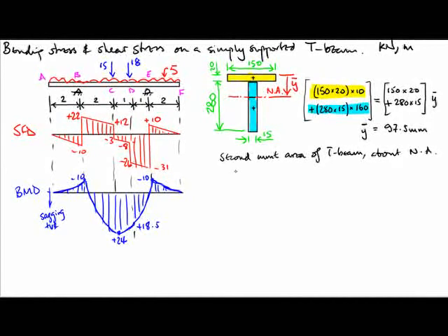For that, we're just going to use the parallel axis theorem, as well as the second moment of area of the individual blocks making up this T-beam.